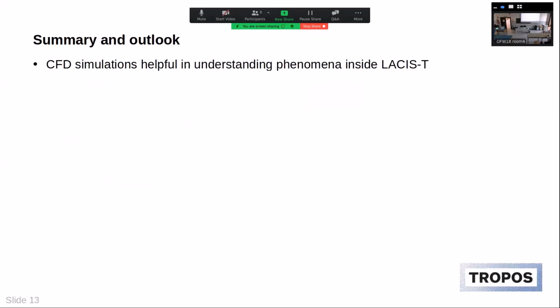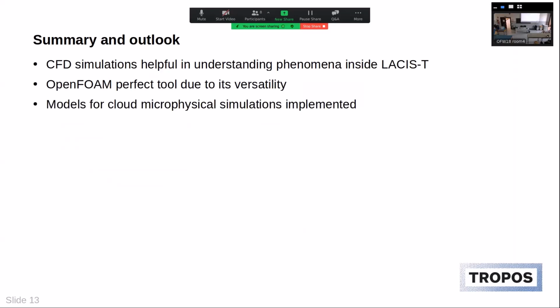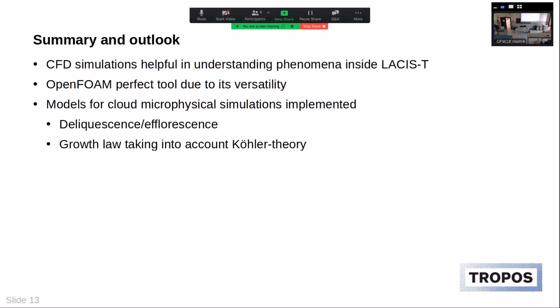We've seen that CFD simulations are helpful in understanding the phenomena that occur inside LACIS-T and also other cloud simulation chambers. And OpenFOAM is a perfect tool for this because of its versatility. We implemented several models for cloud microphysical simulations. Those were a deliquescence and efflorescence model. We implemented the growth law, taking into account the Köhler theory, and we implemented immersion freezing models.